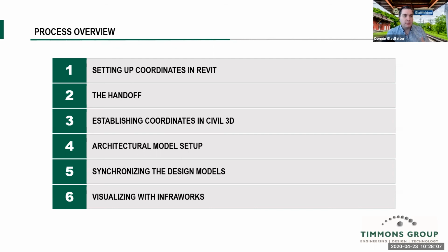It's not necessarily applicable to this scenario where we only wanted to show exterior walls, but maybe I was trying to filter something else inside of a view. I can't even think of something off the top of my head, but if I wanted exterior walls or load-bearing interior walls, let's say, and I had that category or classification as part of the parameters of the Revit families, we could do an OR parameter and see both. But the simple answer to the question is yes, view filters have existed in Revit for quite some time.